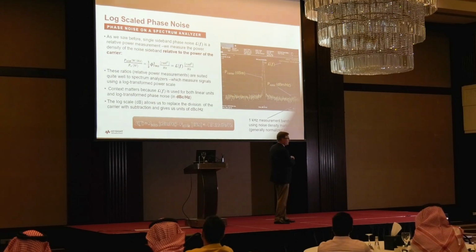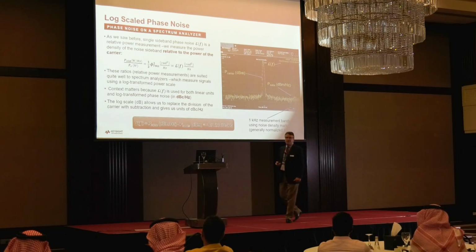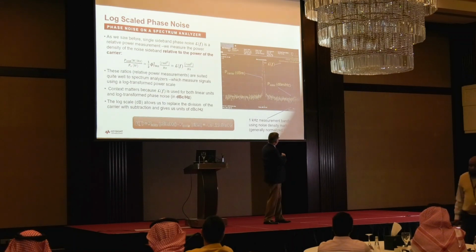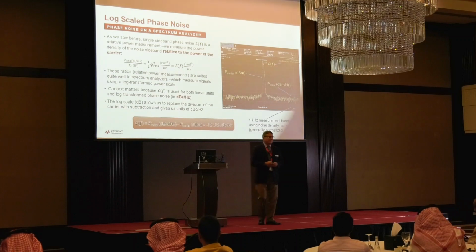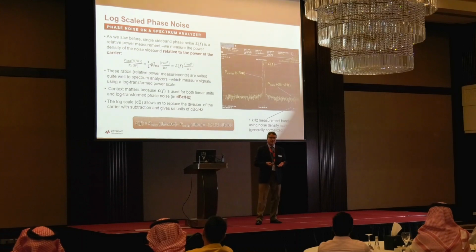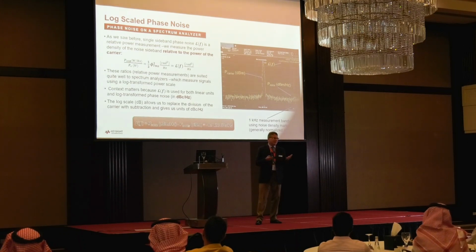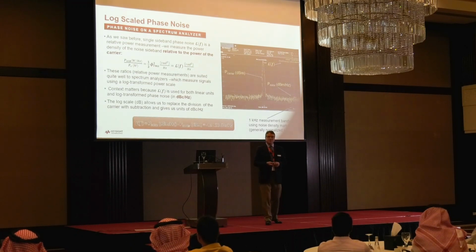And we then just do a very simple calculation with the computer that we have in our instrument, measure that level relative to the carrier, which here we've set at 0 dBm. And you can see that the readout is expressed in dB per hertz here. And then if we do it relative to the carrier at 0 dBm, it will be minus 121.3 dBc per hertz. So that's an example of making a phase noise measurement manually. It's the RMS phase noise translated into the power ratio of dBc per hertz.